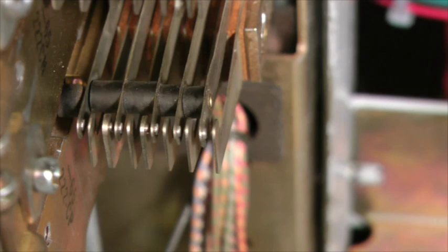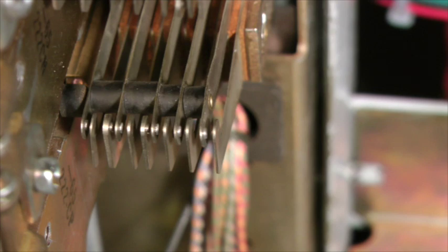The initial operating path for the F relay is through its primary and tertiary windings. The effective flux created by the current through these windings is sufficient to permit the operation of early make contacts 1 and 2, but is not sufficient to overcome the combined tension created by these ganged contact springs.